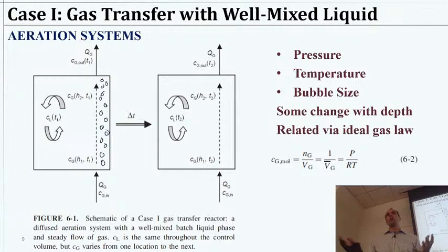Now, by the way, just to kind of call back to the oxygen example, as we saw, our oxygenation works a lot better if we use pure oxygen, but that's a little bit expensive. It's a lot cheaper to just blow air than to blow oxygen, and usually it's determined that it's more than 8 times cheaper, right? Because something like 8 times the difference would be what mattered. If it was twice as expensive as just air, then maybe we do it because we have a big impact, right? But it's not typical to do pure oxygen unless there's some special condition. But it is something that people have experimented with before.